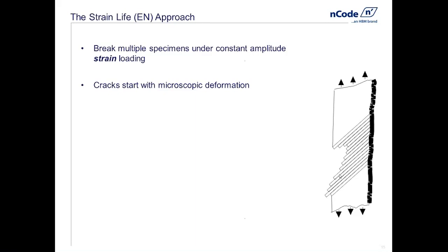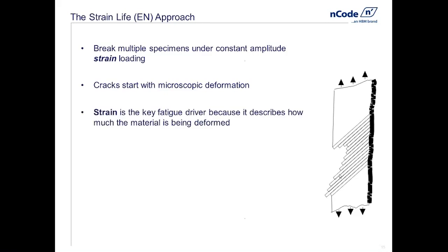Engineers don't typically go looking for microscopic cracks. We look for macroscopic things. We don't calculate stresses in a microscopic way. We don't measure stresses in a microscopic way. We don't use FEA, finite element modeling, with microscopic elements. So this is conceptually what's going on, and you can see from this concept of the shifting deck of cards that it's deformation, it's strain, that describes how messed up my deck of cards is. It's strain that describes the formation of that crack. So really, tracking strain, not stress, is the appropriate way to understand fatigue.